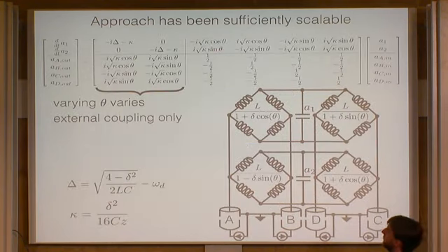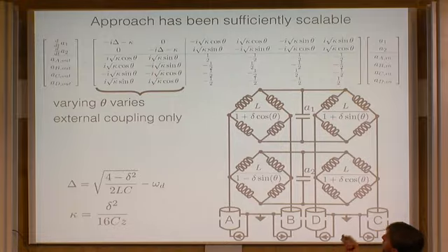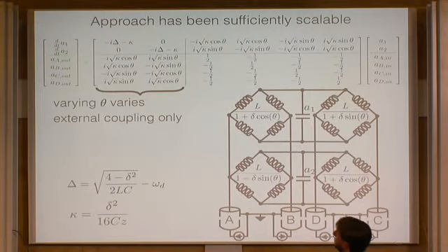And from that, using very ugly, lazy Mathematica code, I can get an input-output compatible model that describes the circuit, where I'm talking now about the dynamics of current through that capacitor, that's A1 and A2, and they're driven through input signals going in each of these ports. That's A1,in, so A, B, C, D,in. And the important thing here is that if you dither these inductances in the right way, that appears only in the external coupling.